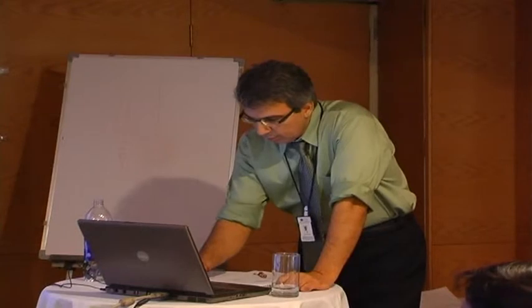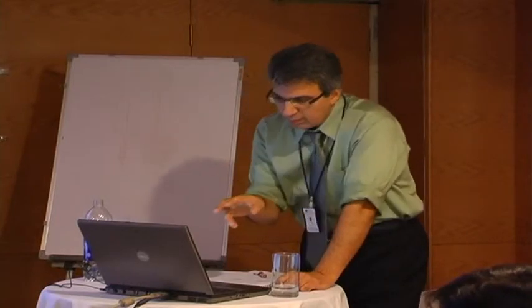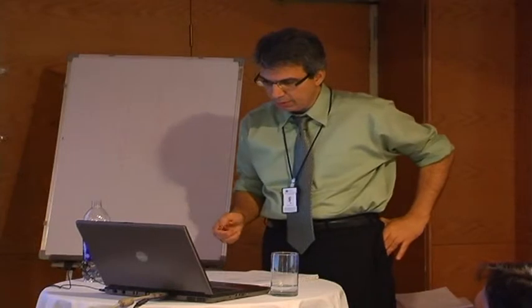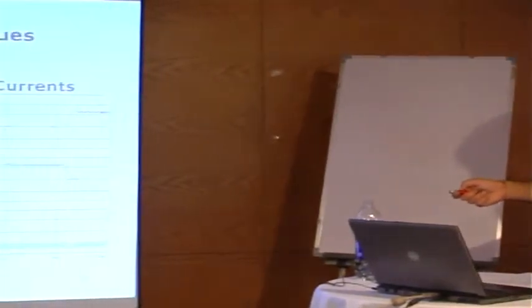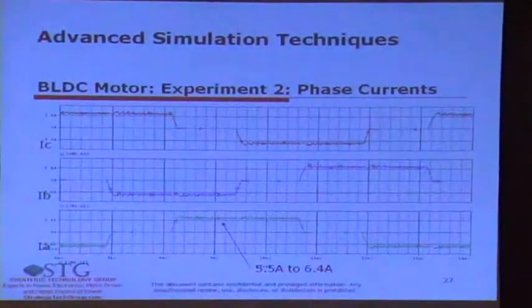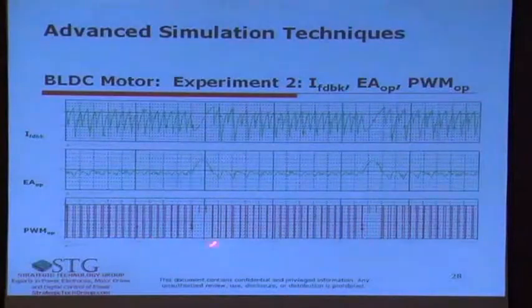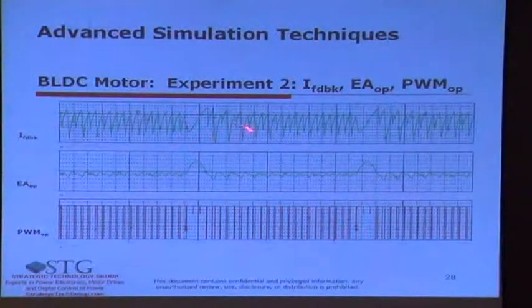Okay. So let's see. Getting back to, we'll come back to this high and low side PWM. This is just a slide which shows the performance with high and low side PWM. You can see the waveforms look a whole lot better than high side PWM. So we'll come back to this when we run the demo. You still see some convergence issues, but PSpice recovers from them. But you have a little bit better behaved feedback signal and error amplifier.